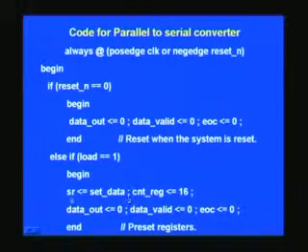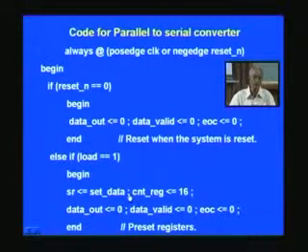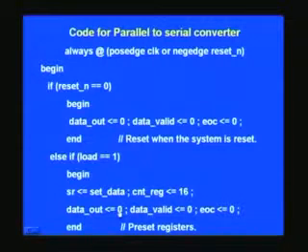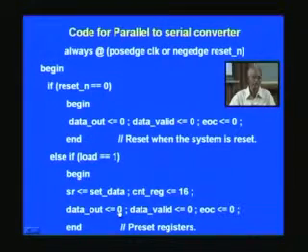And mind you, one statement is complete only with a semicolon. You can put any number of statements here in the same line, or you can fold it just to save space to show in a single slide. I had put it in this fashion. And once again, data out, we don't have to assert right now, because data is not going to be out at this stage. What we are doing at this stage is merely loading the preset value. That's the set data as such.